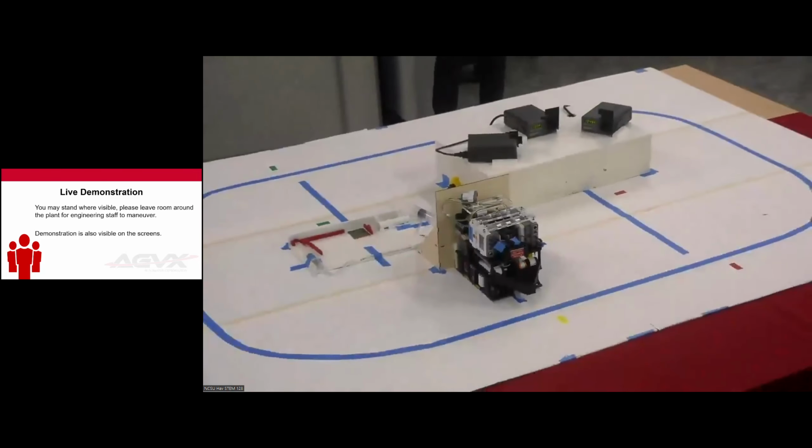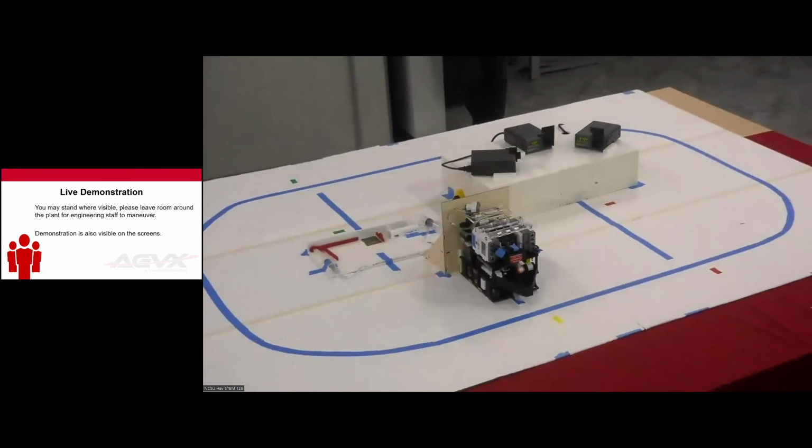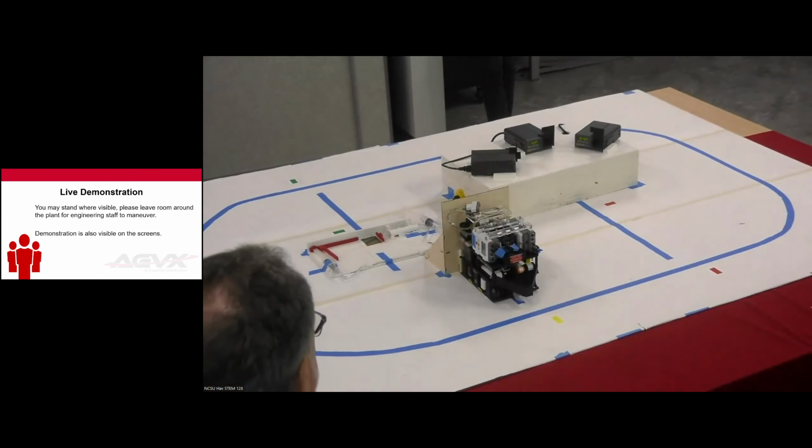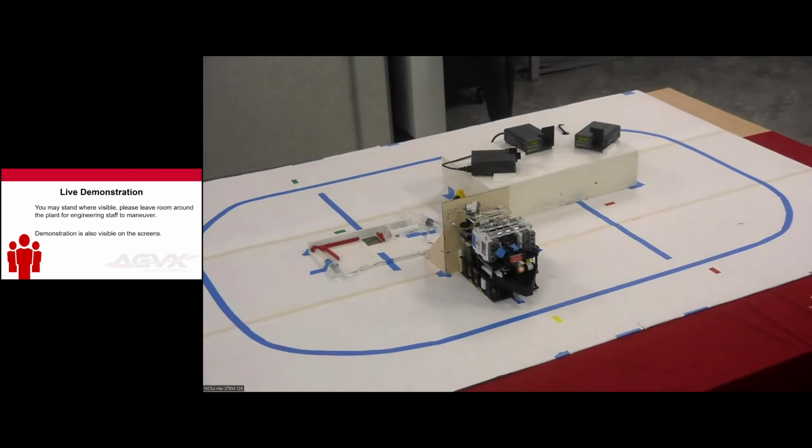One more caveat. If it's in a cell, servicing a cell, there are moving pieces on the vehicle. If you press the e-stop, it will stop before it conducts the next movement. But if it's in the middle of a movement, it will continue to move. It's not a real stop.